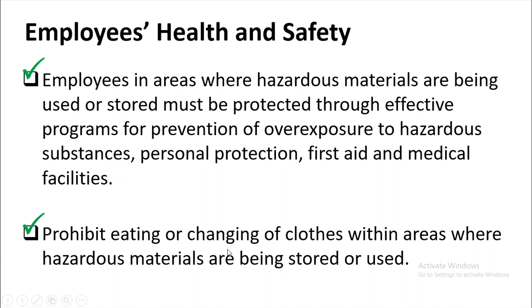So we need to identify a changing of clothes area near the hazardous area but in a secured area, so that when persons go to the hazardous material storage area, they change clothes before entering that area, and before leaving the area they change clothes again, so that they can go outside without contaminated clothes. That is the importance of that changing area for clothes when you are handling hazardous materials.